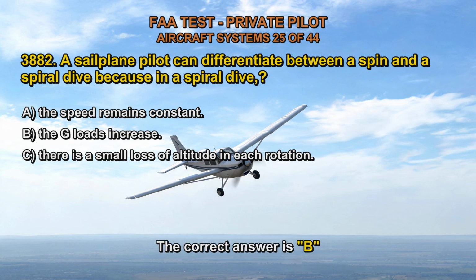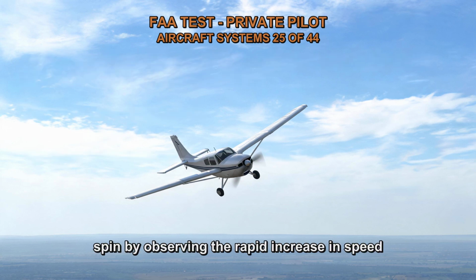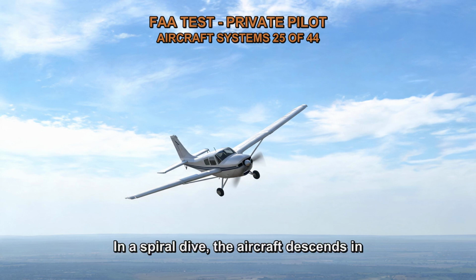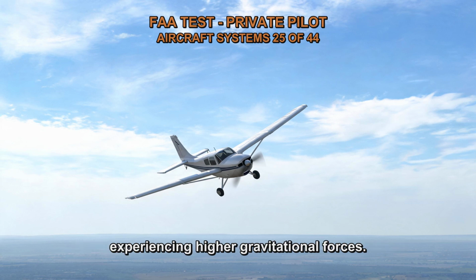The correct answer is B. A spiral dive can be distinguished from a spin by observing the rapid increase in speed and G loading. In a spiral dive, the aircraft descends in a steep, corkscrew-like path while gaining speed and experiencing higher gravitational forces.